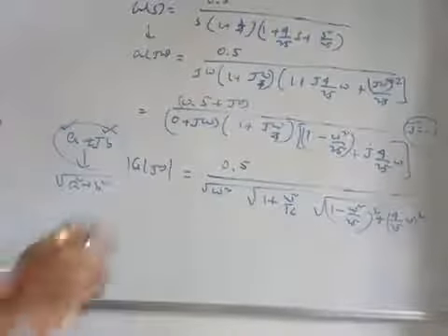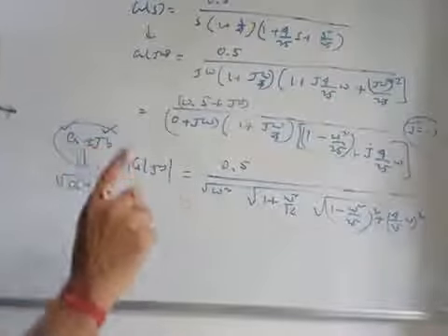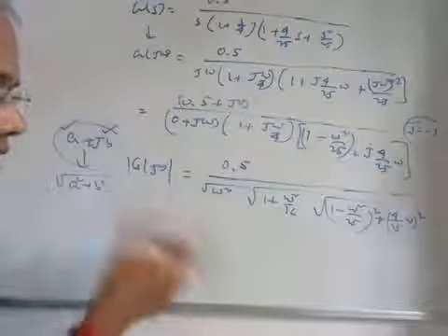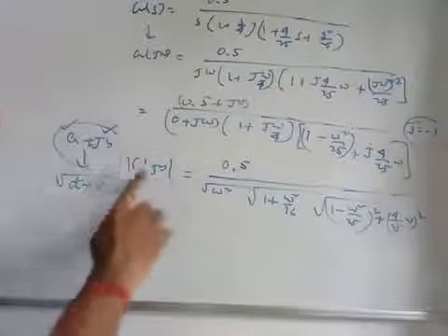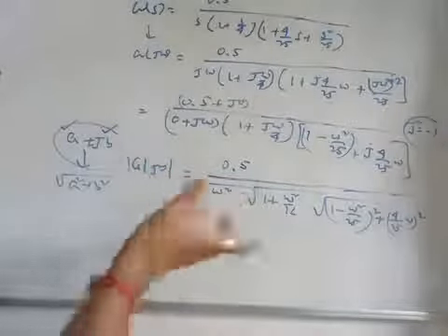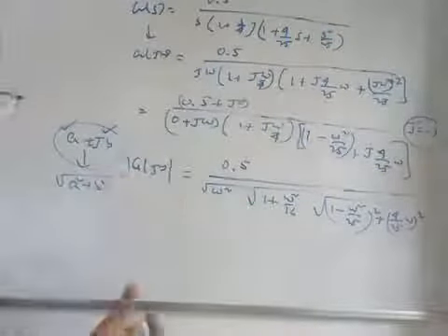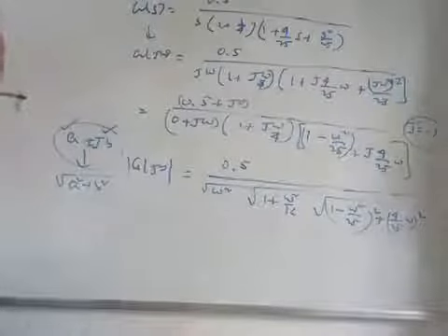So that is the magnitude part, the modulus of this will give you the magnitude. And once you get the magnitude, you have to convert it into decibels. The magnitude in dB will be found by just taking the log on both sides and multiplying both sides by 20. So 20 log of this will give you the M in dB at whatever frequency you require, right?